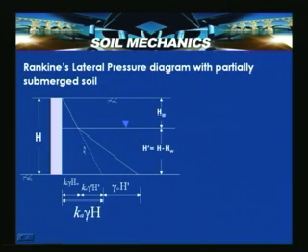Now, below this the soil is completely saturated, with gamma equal to gamma sat, then Ka gamma dash H is the lateral earth pressure here, and gamma W H dash is the water pressure exerted by water of height H minus HW, which is H dash. So, here the total earth pressure is Ka gamma H plus gamma W H dash.